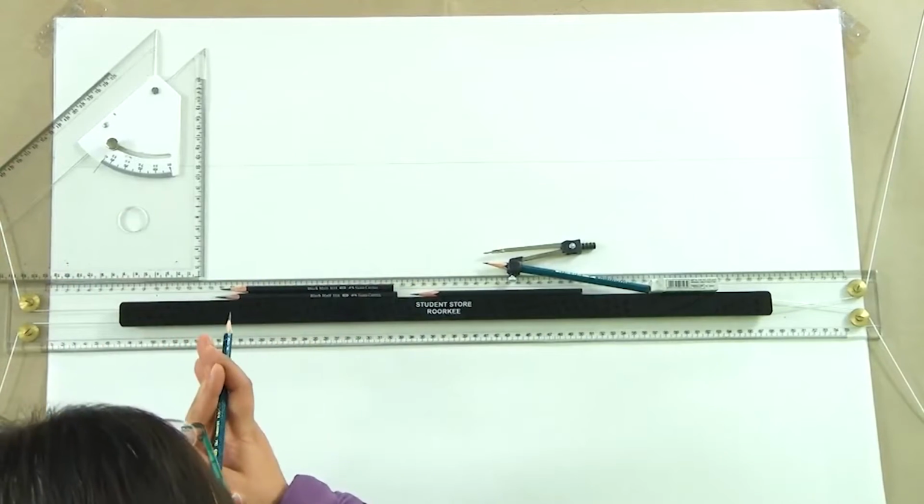To begin with, let us start with very simple solids. Let's assume that there is a rectangular prism which is intersected by a right circular cylinder, cutting it with its axis perpendicular, in such a manner that the axes of these two solids intersect. So assuming that we have a rectangular prism kept on the ground, it is intersected by a circular cylinder perpendicular to its axis, so it will pass through it and actually penetrate this prism. This is a very simple position. We are going to start with that, and then further we will see how we arrive at the more complicated ones.